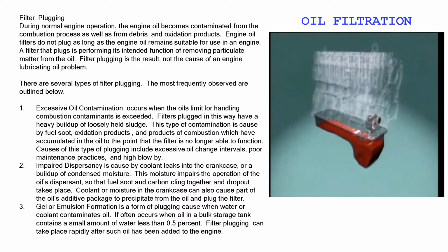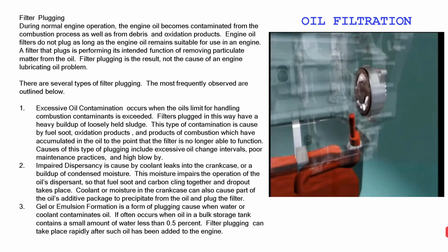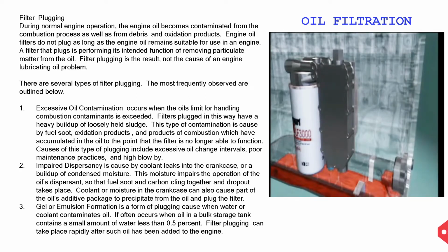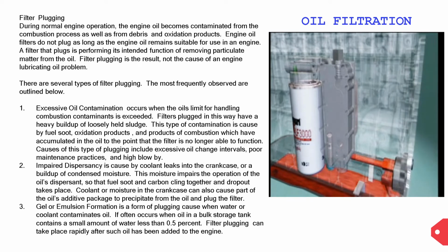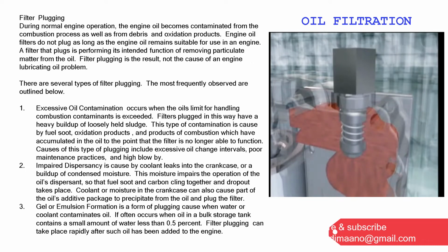Filter plugging. During normal engine operation, the engine oil becomes contaminated from the combustion process as well as from debris and oxidation products. Engine oil filters do not plug as long as the engine oil remains suitable for use in an engine. A filter that plugs is performing its intended function of removing particulate matter from the oil. Filter plugging is the result, not the cause of an engine lubricating oil problem.